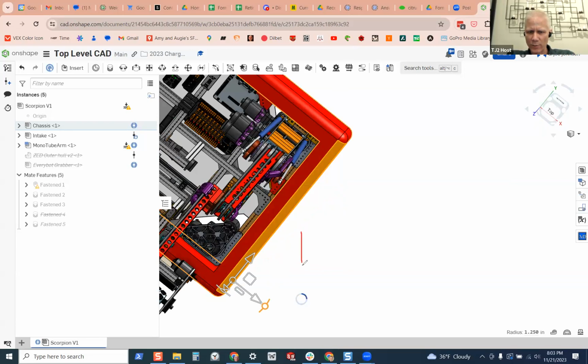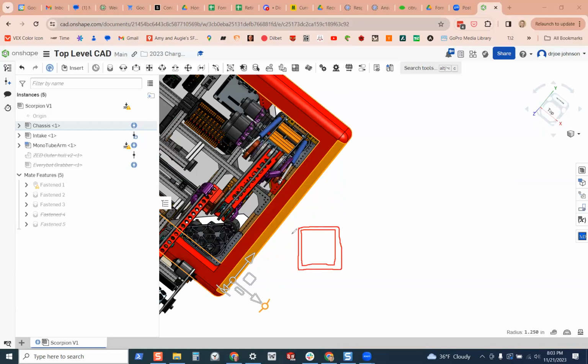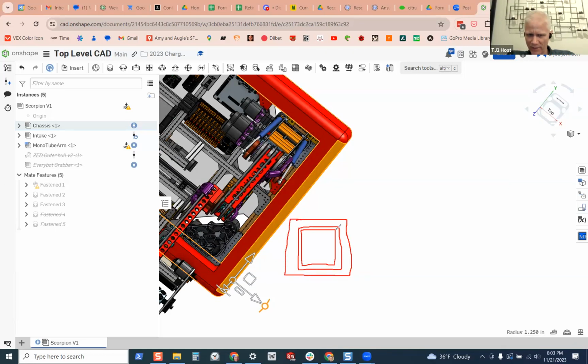So we have a robot that's a square that's 25, and the inside of your square is going to be 25.25. So 25 plus 1/8 plus 1/8, because it's got to be 1/8 of an inch on each side. So that's a quarter, right? And then out here, because this box, the outside of it, if I put a dimension on that, is 25.25.